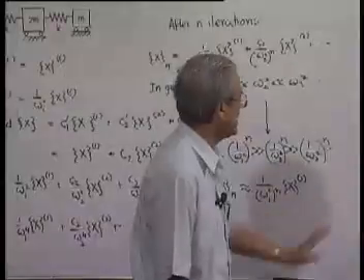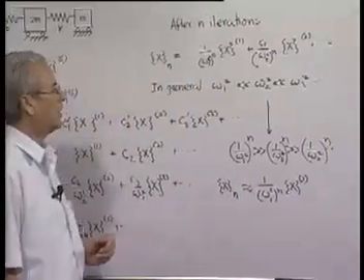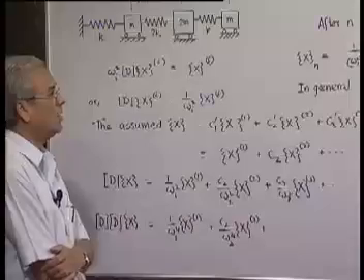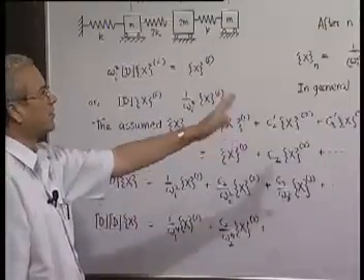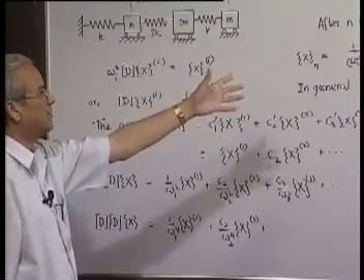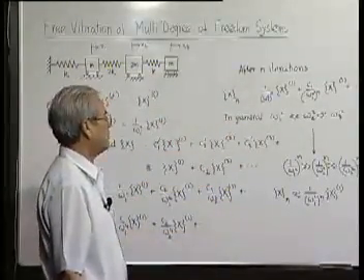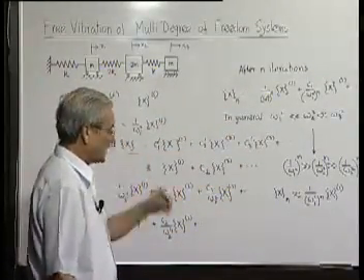So therefore, this is a quick way of getting an idea about the natural frequency and the first natural mode, without solving any matrix equation, because it involves only simple matrix multiplication, which is much easier, and we can do it in quick time. Next, the question comes